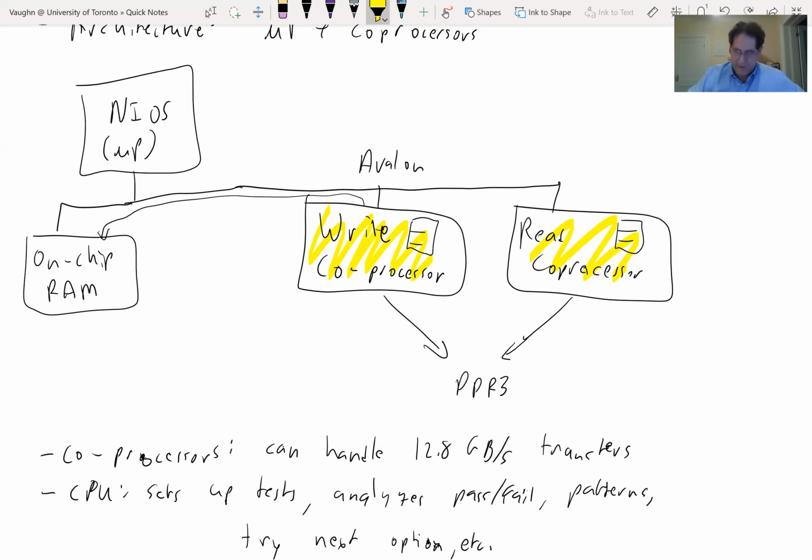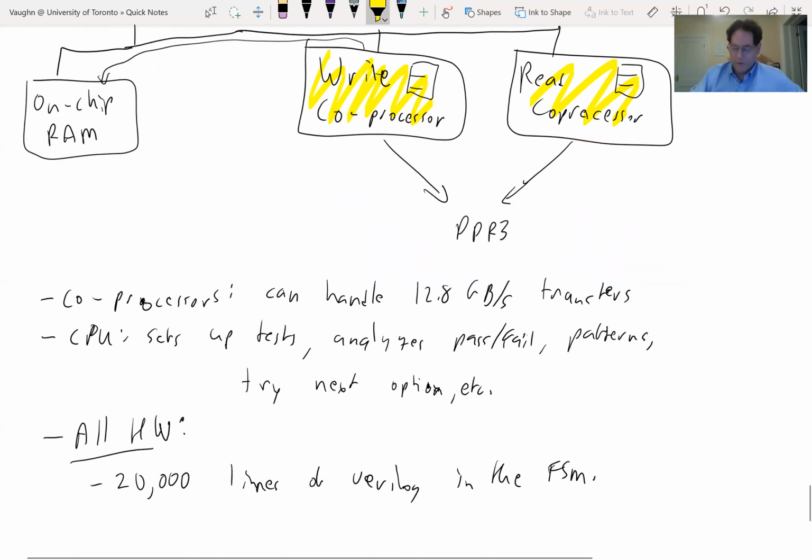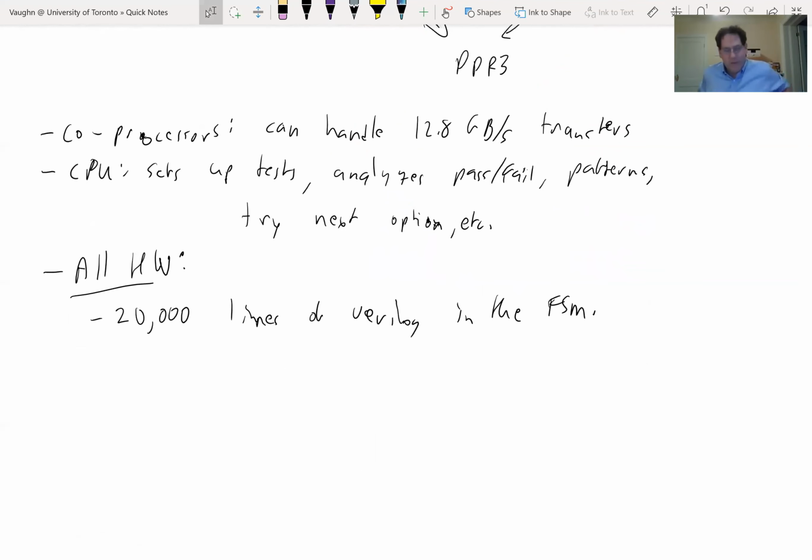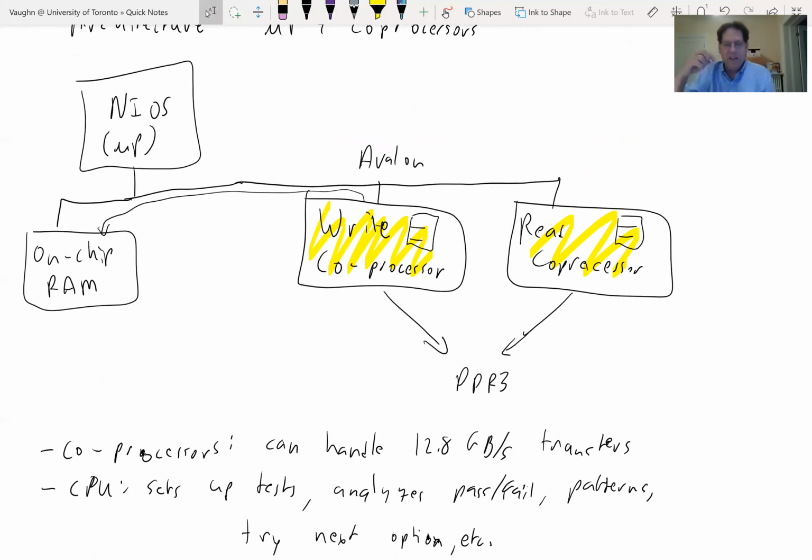Sorry about that. Anyway, it separates the high frequency logic from the lower frequency logic. With this big FSM, even though it doesn't have to run as fast as the data path, it was becoming a problem for it to keep up. So this not only was really hard to maintain and update, it is actually larger than the whole microprocessor. This NIOS design, depending on exactly what you ask for, takes around 1,000 lookup tables and registers. So it's bigger than a typical finite state machine, but not ridiculously huge.